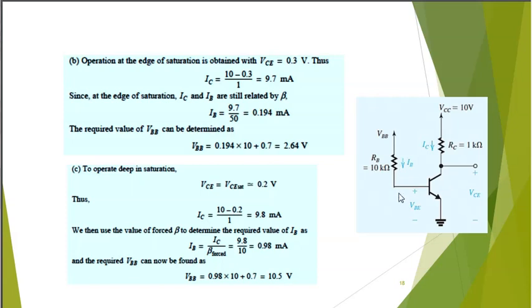So first of all, imagine the circuit is given to you, with VBB given to be equal to 10. So you have to do DC analysis. That's it. When you do DC analysis, you will have two different scenarios. Either you are in active mode or you are in the saturation. You will assume that you are in active always. You assume you're in active and you will try to find IC and VCE. If VCE turned out to be positive, then it means that your assumption was correct and you're in the active mode, safe and sound. So you will find IC, VCE, DC analysis, done.